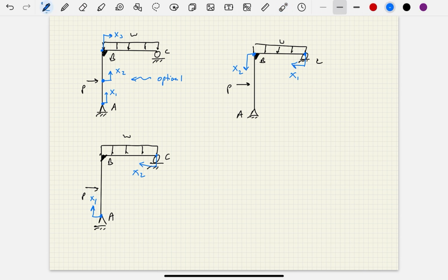Now, the last illustration I want to show is what happens if we have a cockeyed frame. Let's say that we have a cantilever frame, and this frame is at an angle like this, and maybe we've got a point load here or something like that. What should I do in terms of location variables? Well, again, you want to define a location variable generally along a member axis. I think that was pretty obvious from everything I drew in these three examples. We were always defining location variables along member axes.